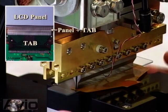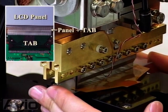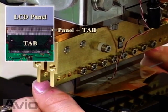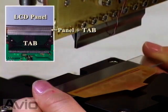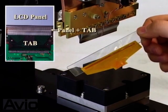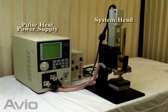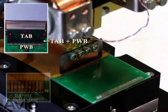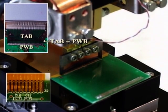While control of temperature, time, and pressure is important in thermocompression bonding, the pulse heat unit from Avio is superior in all these aspects, providing highly reliable bonding. This is a process to solder modules onto glass epoxy-based PWB. Pulse heat method is most suitable for soldering flexible substrate, such as the flexible circuit, without lifting at the joining section.